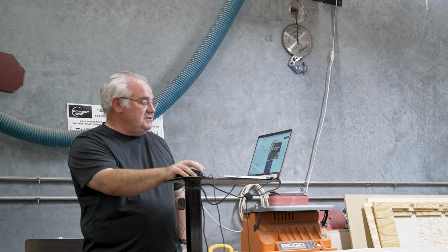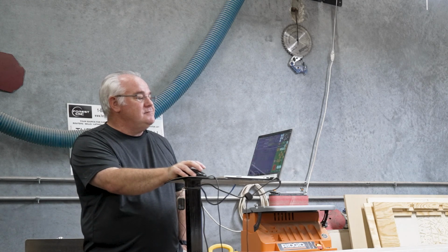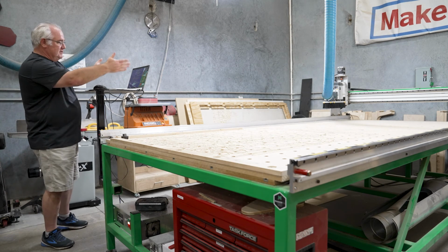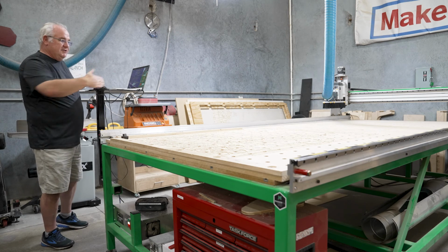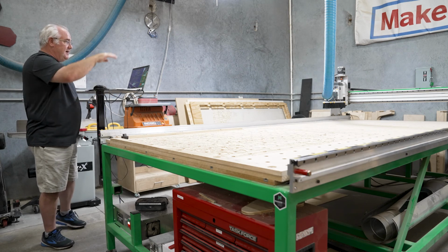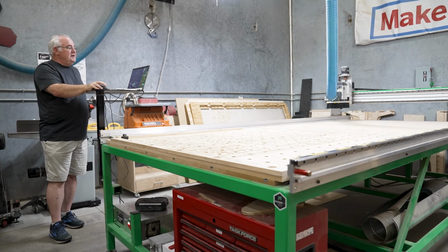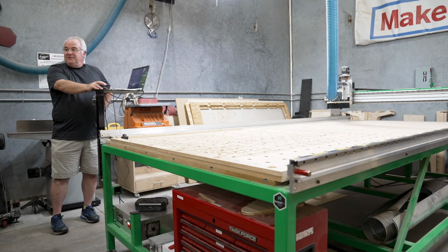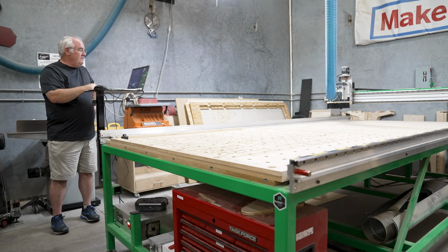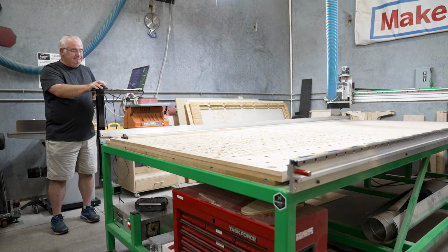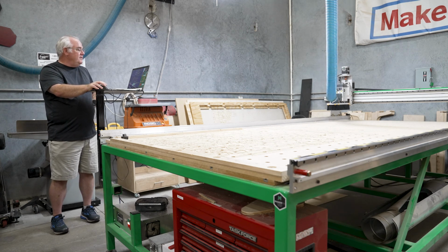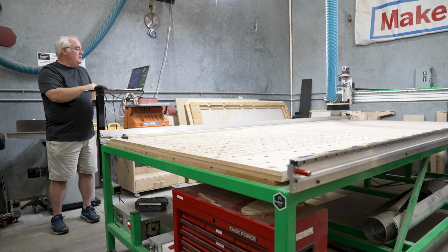The first step is to press reset home, and if you're confused about what's X, Y, and Z, just look at this, as you operate the machine. The Y is this direction, X is across, and Z is up and down. Did you hear that click? Those are the end stops. There are physical end stops for both of the dimensions. So what I'm doing is moving them off of those end stops, so then I can click on reset home.